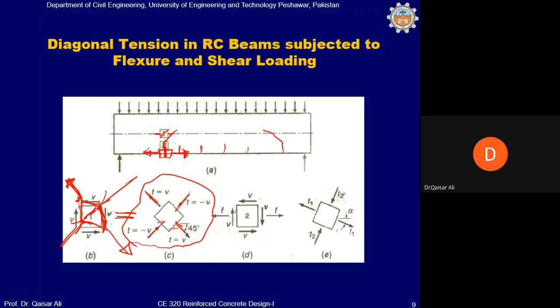Okay, what will be the crack orientation at the midspan of the beam? At the midspan of the beam, shear stress is 0 if the beam is subjected to uniformly distributed load. So the crack cannot turn horizontal, it will be like this, because there are no shear stresses. Even at the mid depth, shear stress is 0 because V is 0, shear force is 0.